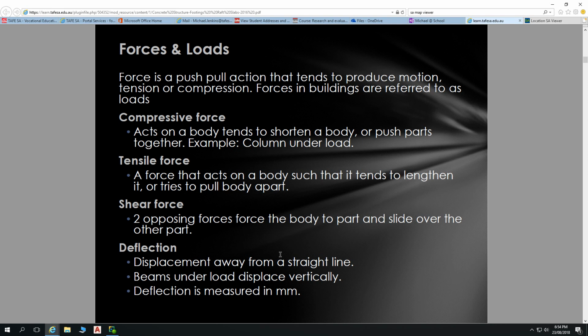And then with our cornices, we ensure that, so we've got our gyprock ceiling lining there, or whatever sheeting product we've got. Got our wall lining there. Those two things have a slight gap between them, so that this one can go up and down. We're just talking about a few millimetres. But in a storm, we've got a few millimetres movement up and down. And then we fix the cornice to the top one only.